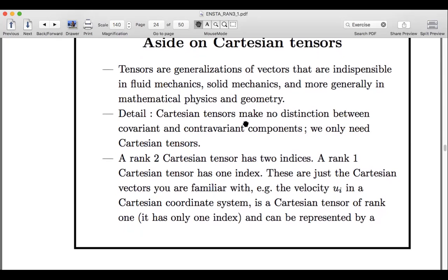If you want to describe a spinning top and its resistance to acceleration when you apply a torque to it, then the generalization of mass that's applicable for when you apply torques, as opposed to linear accelerations or linear forces, is the moment of inertia, which is a rank 2 tensor.